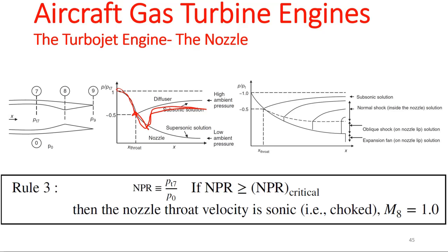Does it make sense? Why is it dependent on T naught, right after T naught? Why is it dependent on back pressure? Because after it becomes sonic, it can no longer see the upstream pressure, so it should be dependent on the pressure at the exit to meet those conditions. That's correct, but both of those pressures are not very close to each other, but are related to each other. When you have a high back pressure, it means that you have a high ambient pressure, right? And here at the exit, you have the ambient pressure. Does it make sense?